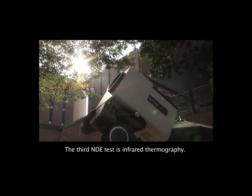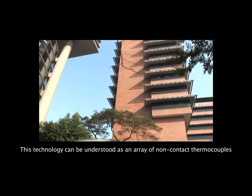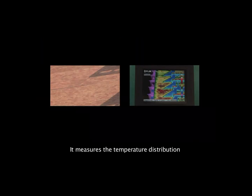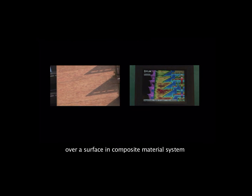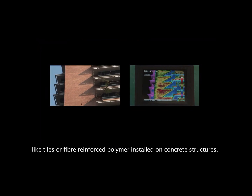The third NDE test is infrared thermography. This technology can be understood as an array of non-contact thermocouples remote from the targets. It measures the temperature distribution over a surface in a composite material system, like tiles, or fiber reinforced polymer installed on concrete structures.